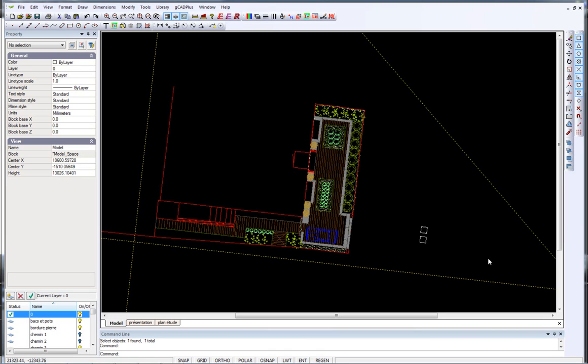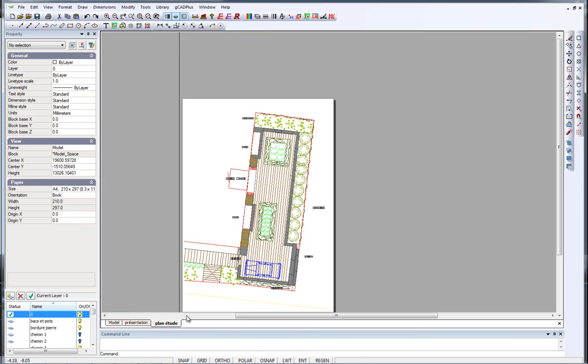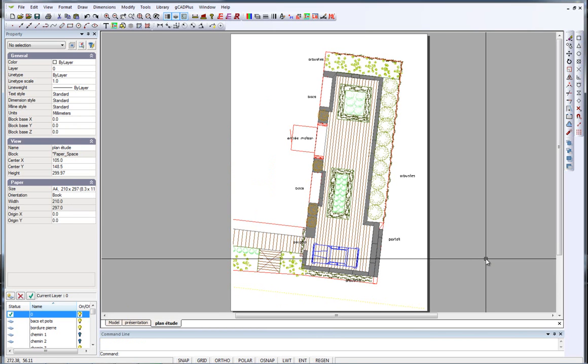It's often useful to twist a design so that it lies horizontally across the drawing editor. The reason for that is if I go into the layout view here and we zoom extends, can you see we're looking at a sheet with an eccentrically placed plan, and it would look a little nicer, I think, if the plan was squared off with the paper.